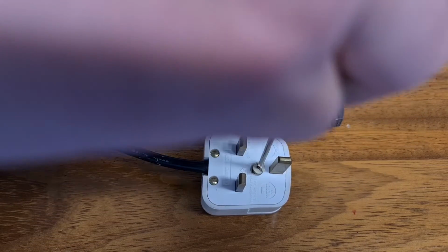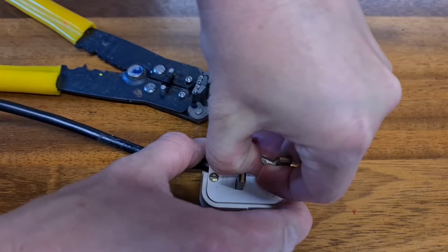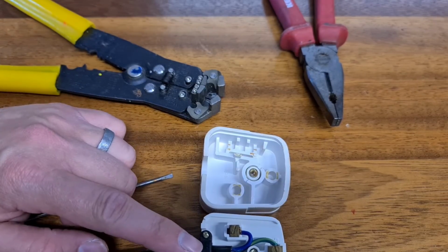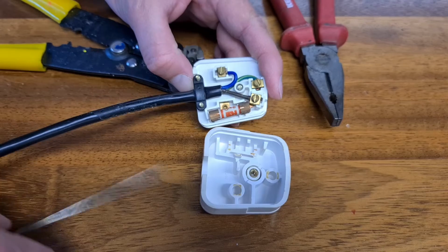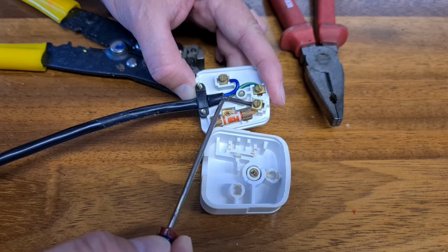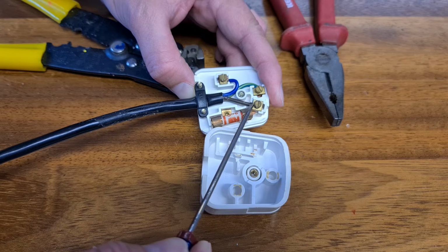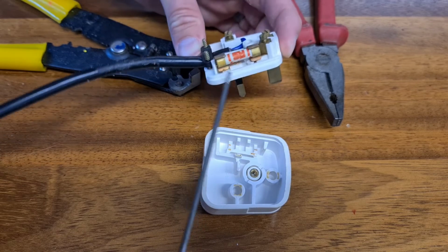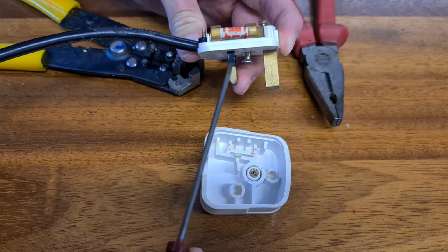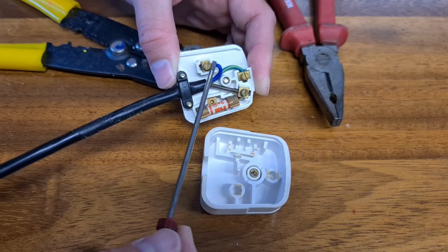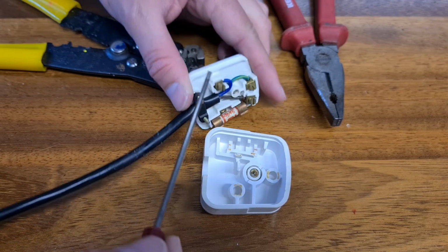So let me get it out completely. And we can take a look at what is inside. So it should release from the case. And there we go. So you can see just here that the wire comes in from the outside. It's held just here. And we have the live wire, this brown wire, coming to this top point, which enables electricity to go through the fuse, before coming out of the pin connected to the live wire, this right hand pin. The neutral wire, this blue one, goes round to the other pin, which is visible just here.